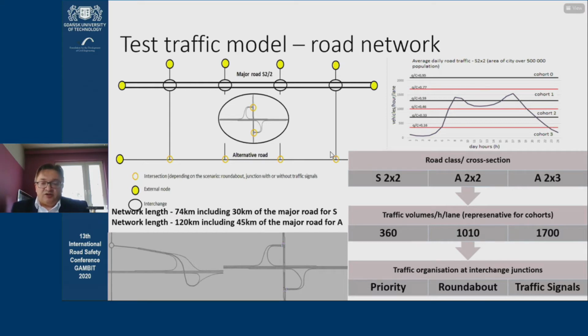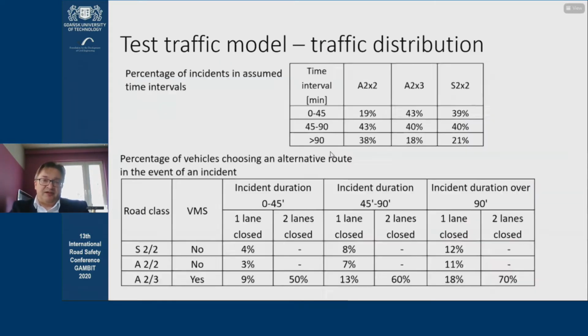We would input different traffic volumes to simulate different traffic movement freedoms. So we parameterized the data using data from traffic count stations, which means that we had access to real data. During the simulation studies, we simulated situations such as incidents on the main road, and that meant difficulties, for example, reducing capacity, depending on whether we needed to close off entire roadways or lanes.